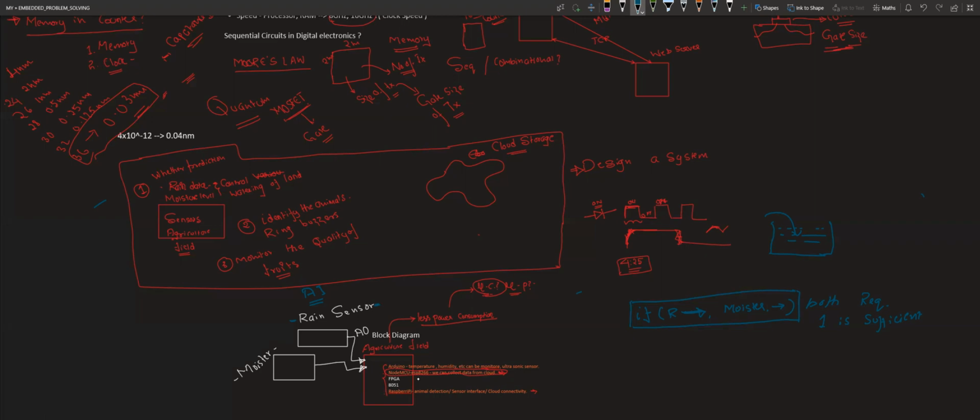Another important thing is driving this pump whenever the moisture level falls. So instead of an LED, you have to drive the pump. My next question is, if I want to drive this pump, is just plus 3 volts sufficient? Assume the pump is an inductive load.